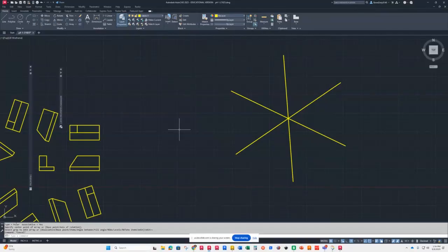If you do a polar array, 99 times out of 100, you need to turn off associative. Well, I won't say 99%. Well, a lot of times you do, unless it's just circles. Like if it's just holes on a bolt circle, then yeah, leave them associative.